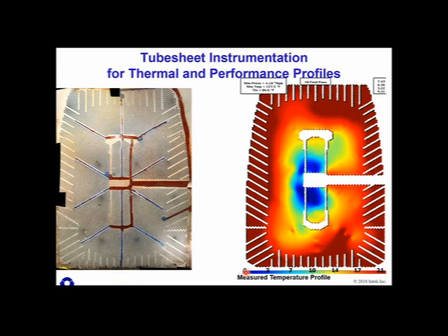So blue is 0 degrees temperature rise of the cooling water going from inlet to outlet. 21 degrees is 21 degrees temperature rise from the inlet to the outlet. So here on the periphery, you know, it's very high velocity steam. There's very little condensation out here. We have high heat transfer coefficients. We have 20 degrees temperature rise. But look at this dead zone in here.